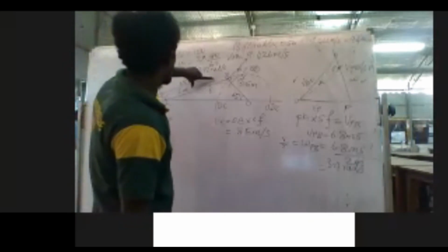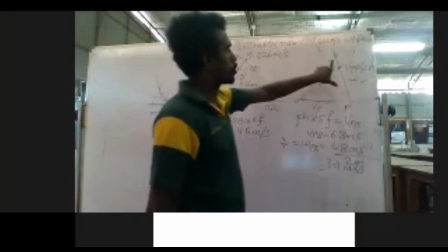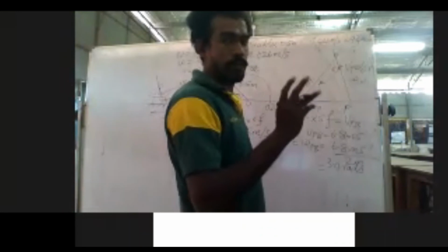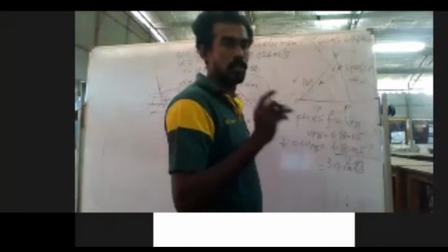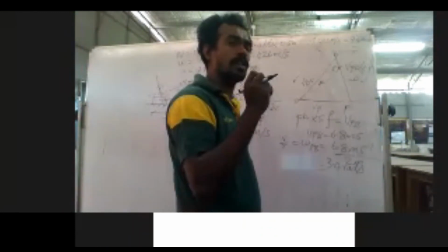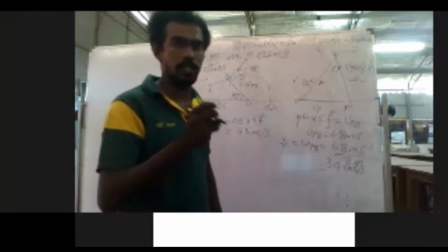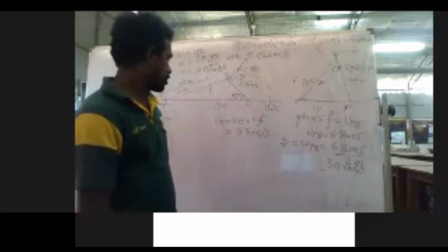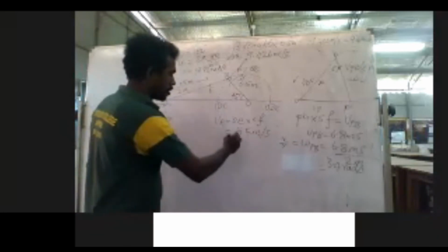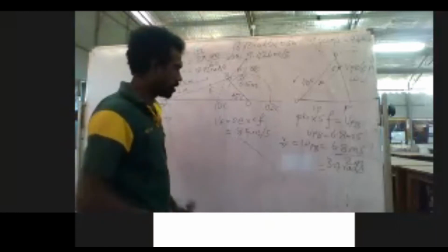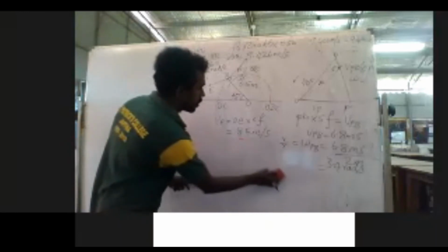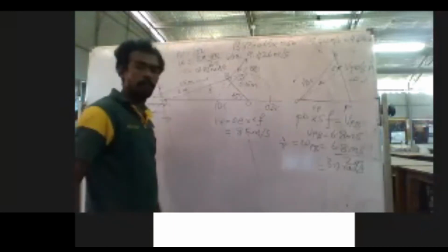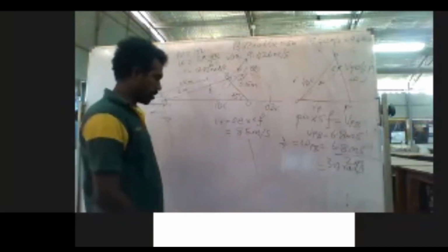So this is again related to the connecting rod, that is PB. So now I have to do something with this length. I need to mark first where the G is. It's only said which point will have the least velocity, so I need to mark that particular point. I don't know where it will be. From a point to any arbitrary line, the minimum distance is the perpendicular of that line to the point.